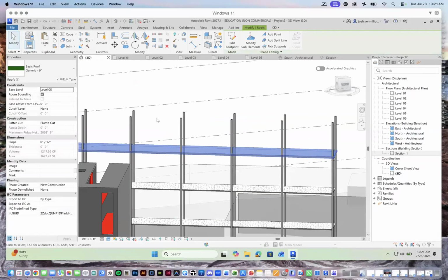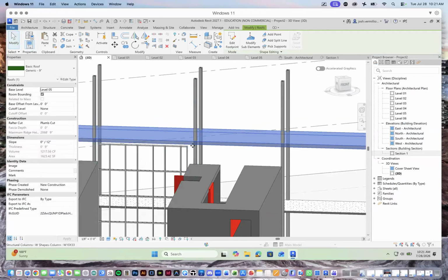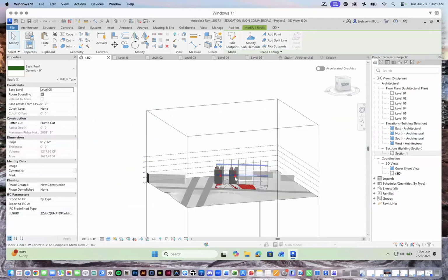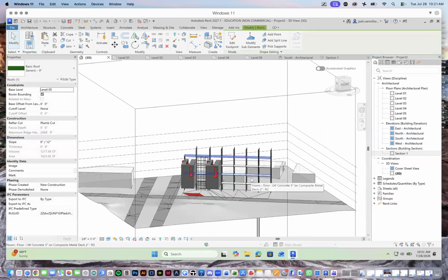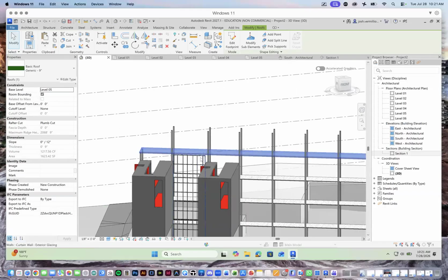But what I'd want to do is make sure that these things actually close up, right? So I'd pull this part of the roof out and over, and then keep the curtain wall at this point going over, going back. So again, it's not foolproof. You do have to figure out things. Things have thickness to them. That's one of the bigger things you start to key into when you're starting this process of building the building information model in Revit.